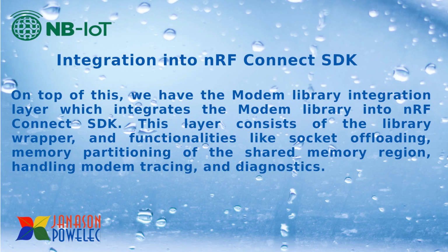Integration into nRF Connect SDK. On top of this, we have the modem library integration layer, which integrates the modem library into nRF Connect SDK. This layer consists of the library wrapper and functionalities like socket offloading, memory partitioning of the shared memory region, handling modem tracing and diagnostics.